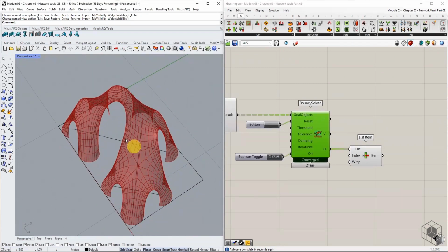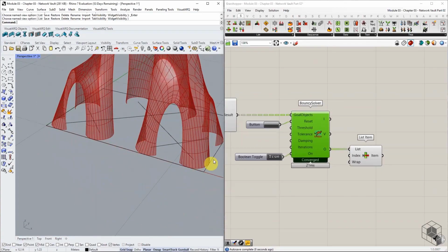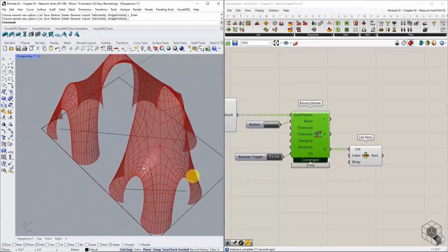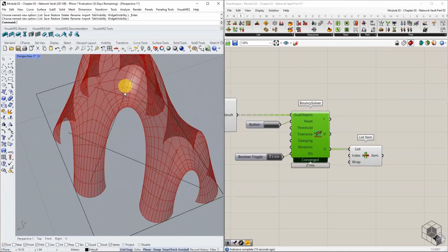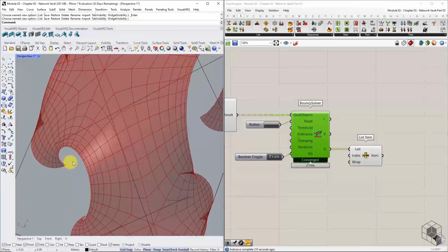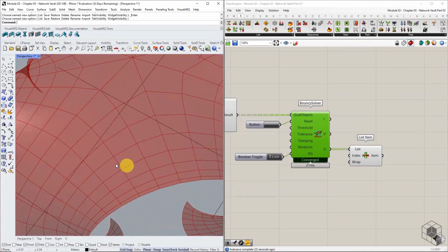The simulated mesh is anchored at the target mesh as expected, and the mesh converges into a network of vaults. The naked edges and adjoining faces are skewed in proportion, giving an undesirable fold at the top. This is subjective as per personal preference.